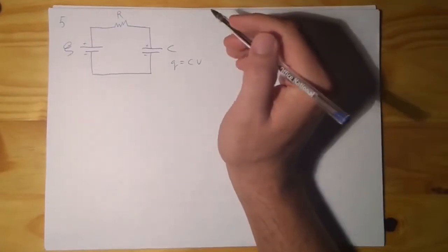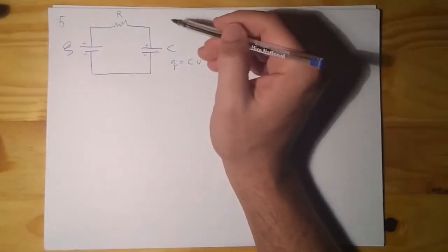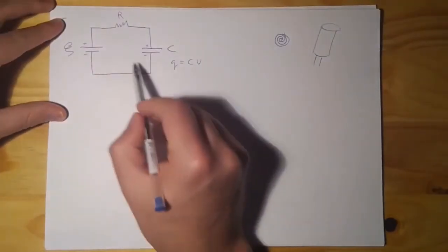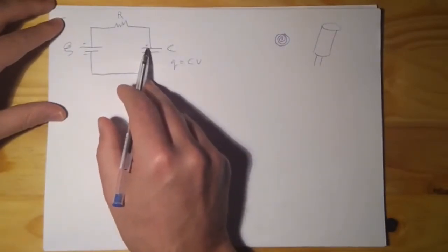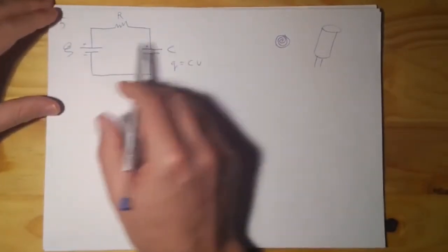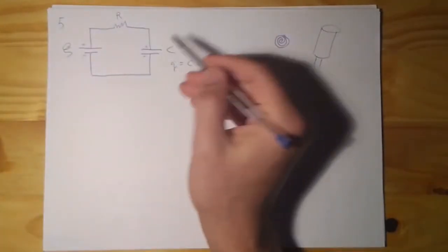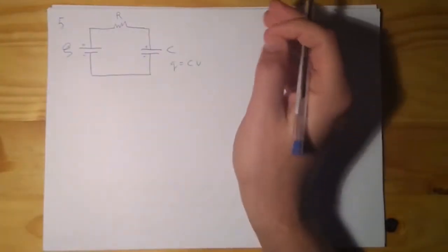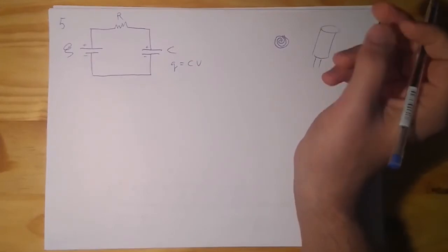We're after a differential equation, so that means necessarily something is changing. And what is changing in this case? It is the charge on the capacitor. As soon as you close this circuit, it's not immediately going to reach its maximum charge. It's going to be a gradual process. The electrons are going to stream to the one side and away from the other side. So by setting up the differential equation, we'll be able to look a little bit more closely at how that happens.